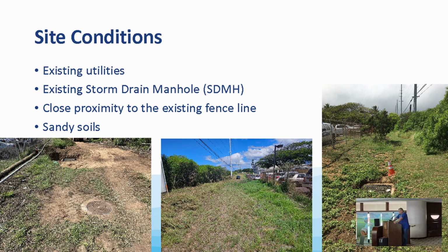The subsurface soils at the site are mainly comprised of medium dense to dense sand, with traces of silt and gravel. Sandy soils in the area have a significantly higher infiltration rate. Infiltration tests were conducted as part of the geotechnical soils investigation and calculated infiltration rates at each test location, and both exceeded 24 inches per hour.